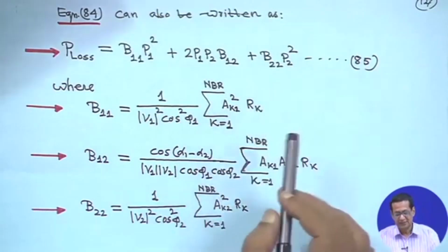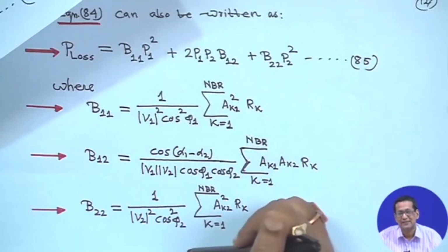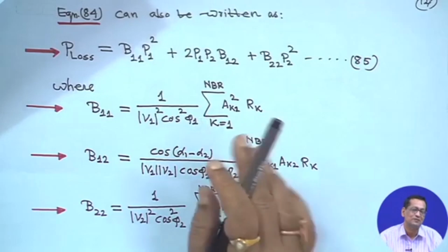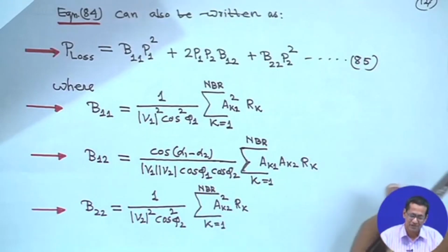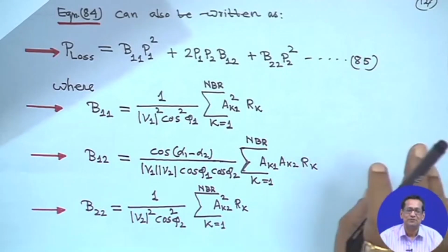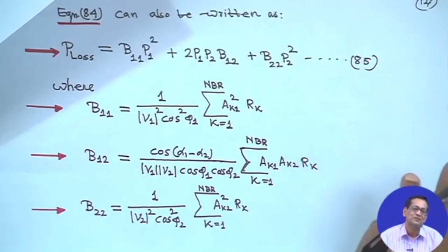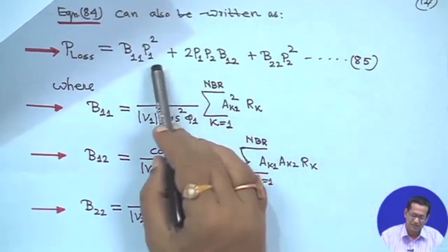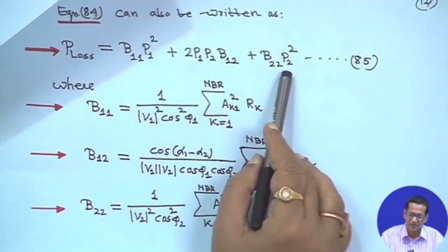So, listen to one thing, this P1 and P2 are actually generator 1 and generator 2, no question of slack bus, just a count of your generating power, that is Pg1 and Pg2. Actually, this P1 P2 is nothing but Pg1 Pg2, right. So, only 2 generating units, but when you do it in general, of course, you have to see Pg2, Pg3 up to Pg m, right.